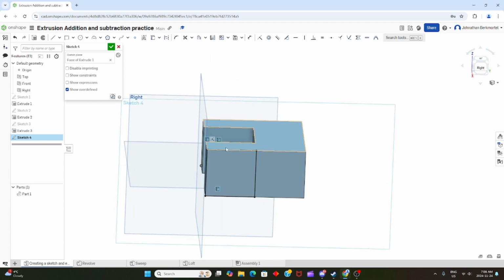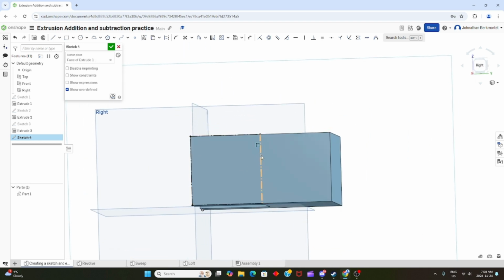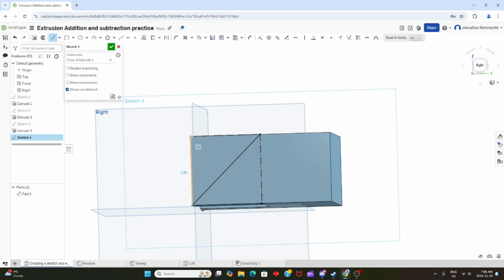But we don't want to just blindly cut that. So let's highlight this and use another tool within the drawings, which is construction geometry. So it'll change all your lines into construction lines, which means when we go to cut it, it won't actually use any of these lines. We only have to worry about them as references to our main drawing. So there we go. Now you can see it's changed over to these center lines, which is just our construction geometry line. And now when we go to our line, when we want a nice slope, we can go from corner to corner, and now we can just close this off.